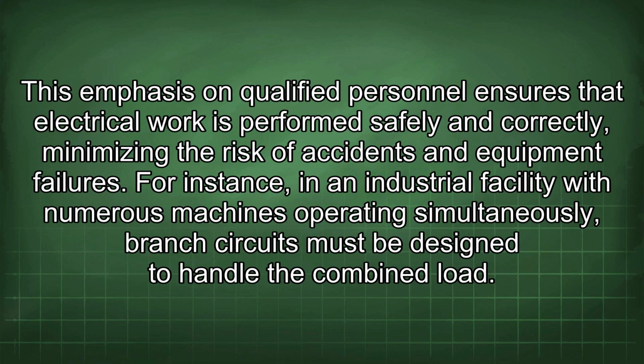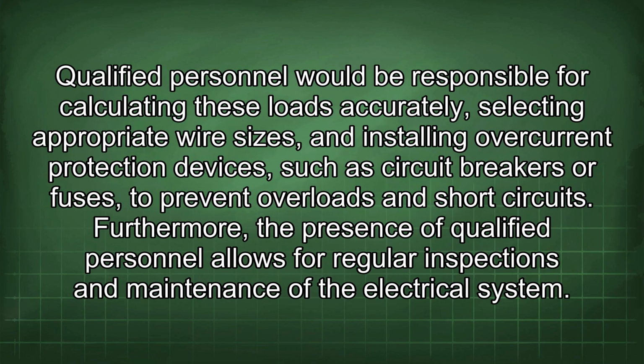This emphasis on qualified personnel ensures that electrical work is performed safely and correctly, minimizing the risk of accidents and equipment failures. For instance, in an industrial facility with numerous machines operating simultaneously, branch circuits must be designed to handle the combined load. Qualified personnel would be responsible for calculating these loads accurately, selecting appropriate wire sizes, and installing overcurrent protection devices such as circuit breakers or fuses to prevent overloads and short circuits.